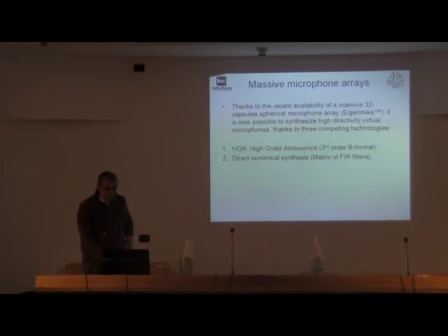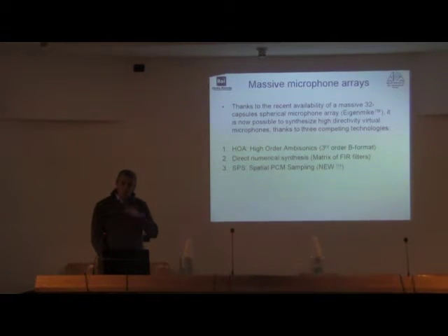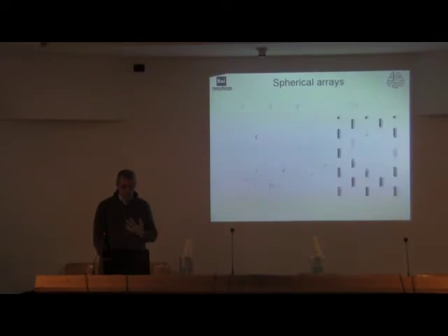The Eigenmike is a high-order Ambisonic, third-order, A-format array, but we developed a different technology for deriving virtual microphones from it, which is direct numerical synthesis, a matrix of FIR filters, exactly as we did with the tetrahedral probe for making the B-format signal. And now we have a very new approach, which is called spatial PCM sampling, and I will try to explain it very quickly to you today. The time is short.